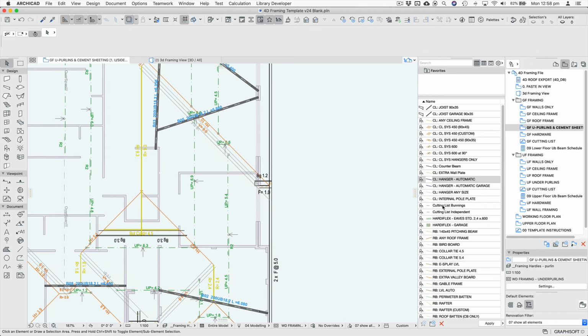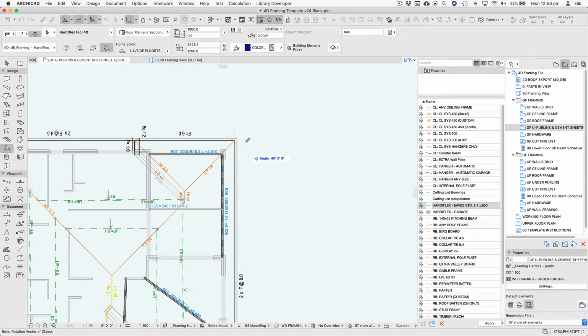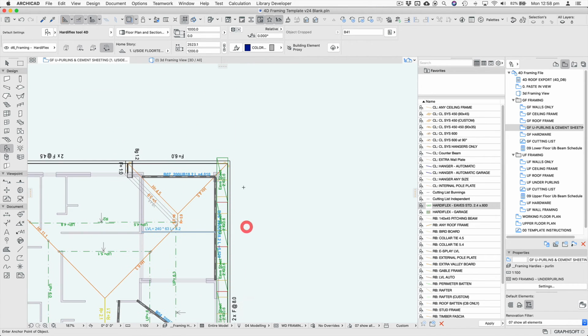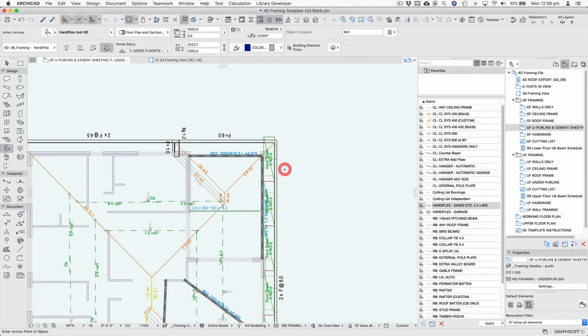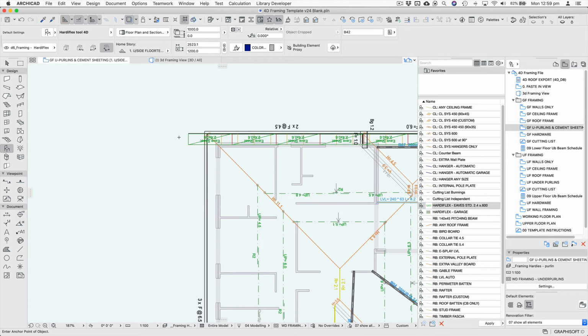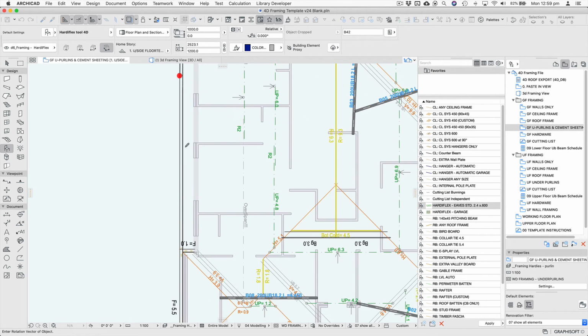Okay, first off, let's do the eaves. I've got a favorite here for my eaves. Stretch method. I always go past a bit. So the eaves will create a whole sheet at each point. So I always go past to see where that whole sheet finishes. So we've got a bit of offcut there. That's fine. I'll just start on the inside of that one.